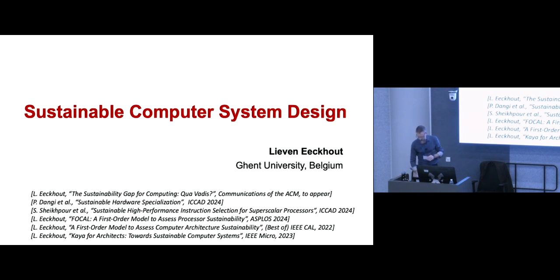Well, if you compare one specific DSA implementation versus a CGRA, the CGRA would consume much more chip area than one DSA. But the point is that to support many different applications, you need multiple DSAs. So the total chip area for all those DSAs would be larger than this one reconfigurable array that you can reconfigure on the fly as new applications come in. And so the chip area of the CGRA would be much smaller than the sum of all the DSAs that you would have. That's where the benefit is coming from. That makes sense. Yeah.